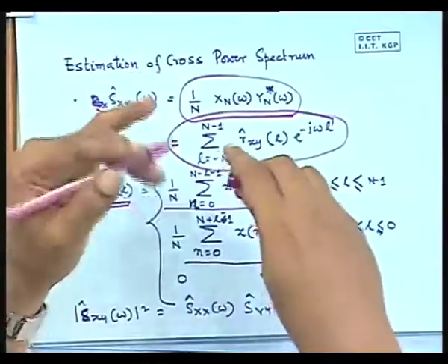Both are possible. And if you look at DSP books, you will find that there are lots of window functions. There is something called a window function in DSP, which is used to convert finite length sequences, one sequence into another, and based on the properties of the window function, you get certain properties in the frequency domain. So there are very nice window function interpretations of many of these operations. If you are interested, you can see that, but we don't have so much time to cover all that. So we'll stop here today.